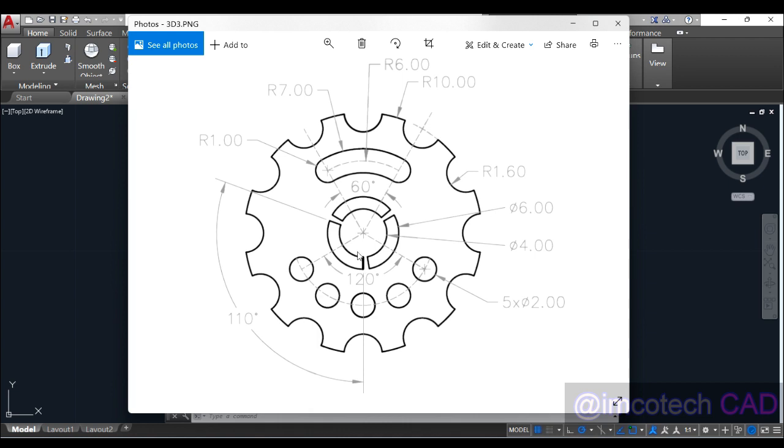There's an angle of inclination for this design, and that angle is 110 degrees. So I'm going to draw a vertical construction line, then draw a normal line at an angle of 110 degrees to this vertical line, and by that I will cut out every external part. Let's watch and see.